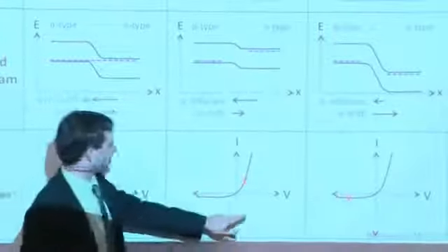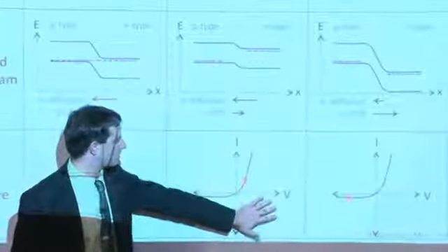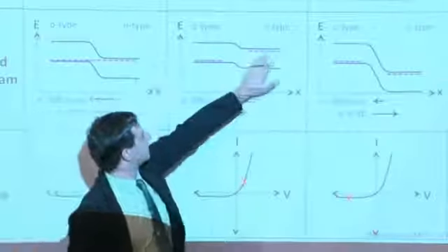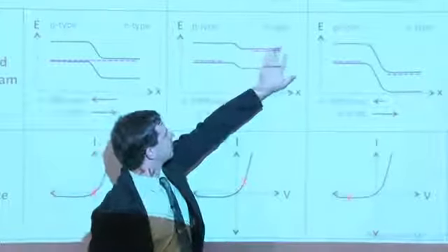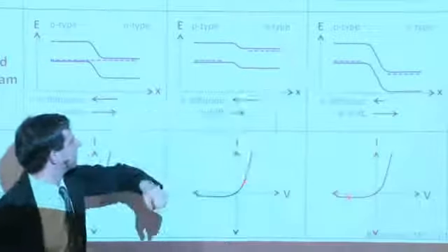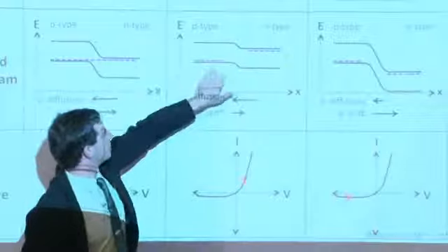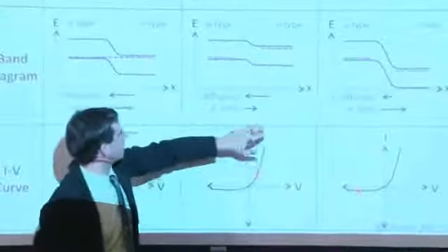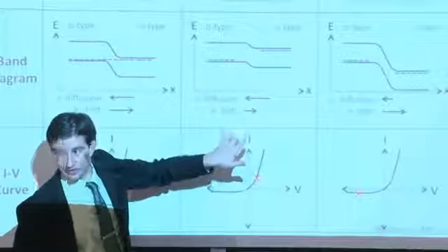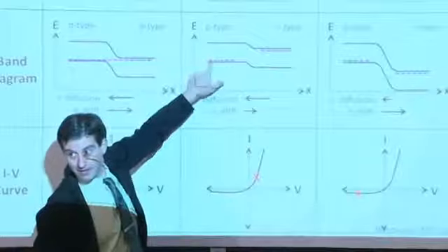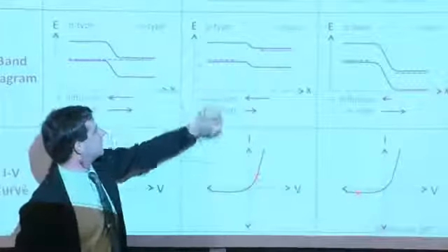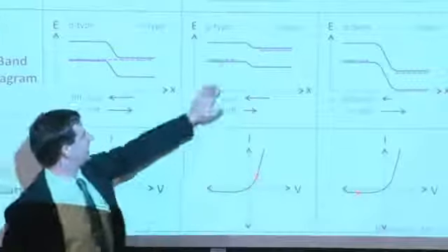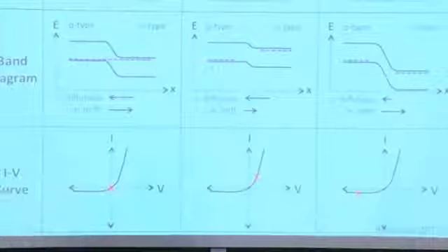So this we call the fourth quadrant, typically 1, 2, 3, 4, fourth quadrant. This is where power is coming out of the solar cell device. Because if we imagine instead of having a battery there, we have a resistor, the electrons will travel from the N-type material through that external load to get to the P-type material where their chemical potential is lower, right? Because they'll desire to minimize their free energy. And as a result, they'll deposit that power across that resistor, across that external load, in order to get back to this other side, because that's the only path that they can travel easily, right? And so this entire curve shifts down. You have your red X somewhere in this quadrant over here, and power is flowing out of the solar cell